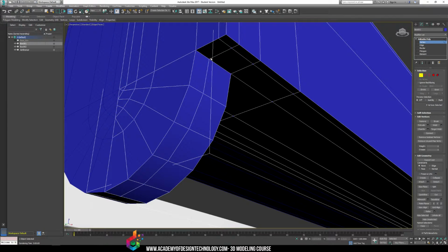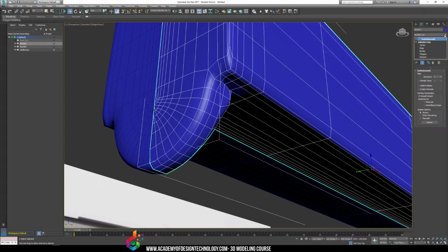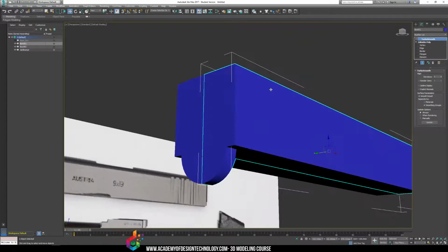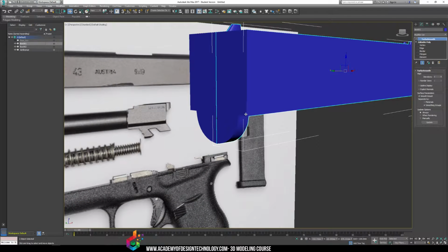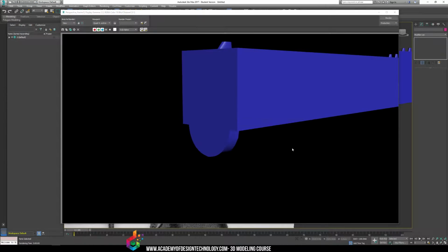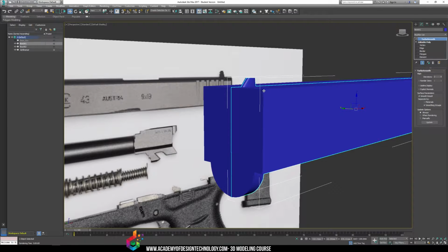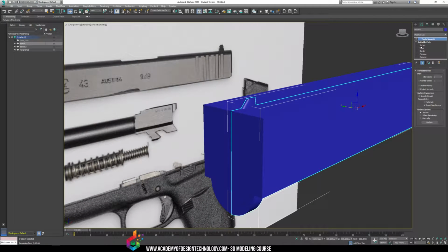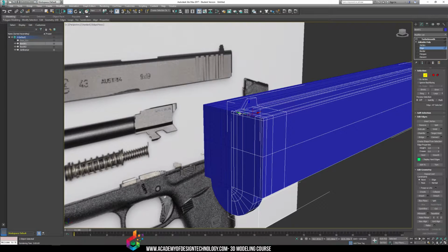So these two vertexes are now welded. So now if they turbo smooth, that'll turbo smooth much better than it did before, once we separate by smoothing groups. Everything's a different smoothing group right now except for the stuff I extruded. But you can see we get a smoother look here. So with turbo smooth on, it looks like this with the different smoothing groups. So it's just a matter of me assigning the different smoothing groups now to where I need it, and obviously doing chamfers and stuff like that, because if I start chamfering, I have a low poly amount.